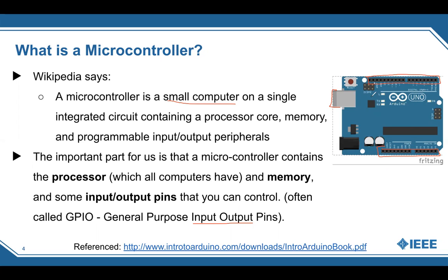And so looking at the Arduino here, the most popular ones you'll see when you use are these digital pins. So we have 13. If you look at the board, it starts here at 0 and goes all the way up to 13. And then we have a ground, and you'll notice some of these have little wave symbols next to them. That means pulse width modulation for a duty cycle. So how much the voltage is applied. So the voltage might occur here, be high, and then the voltage will go back down and be off, then it occur and be high again, and then go back off.